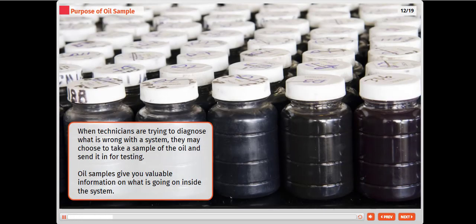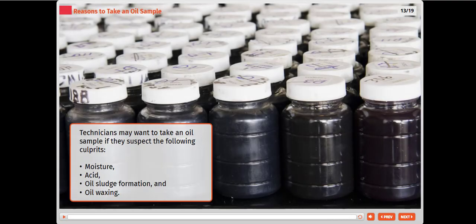When technicians are trying to diagnose what is wrong with the system, they may choose to take a sample of the oil and send it in for testing. Oil samples give you valuable information on what is going on inside the system. Technicians may want to take an oil sample if they suspect the following culprits: moisture, acid, oil sludge formation, and oil waxing.